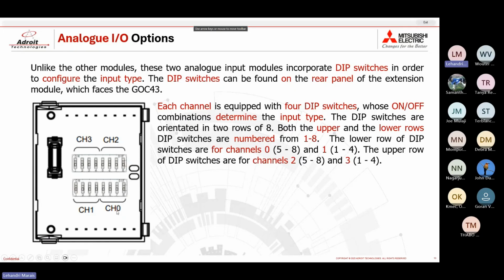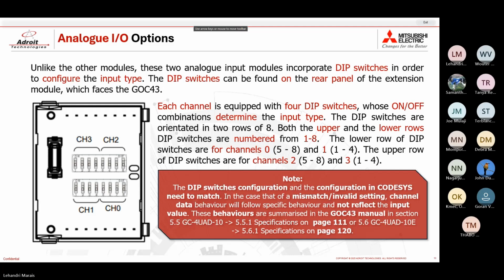Each channel has 4 dip switches, and these dip switches, depending on whether they are on or off, configure an input type. Now, your dip switch configuration does not mean that you don't configure your input types within CODESYS.